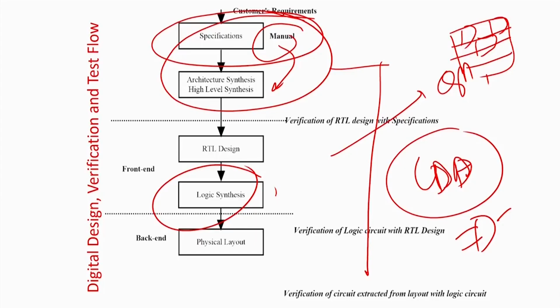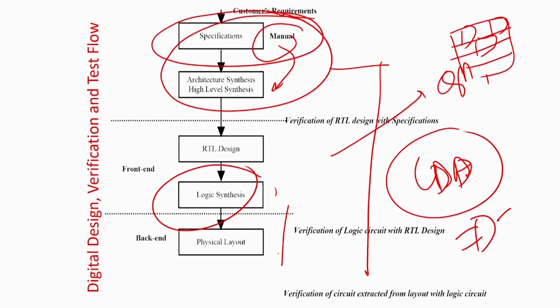If you want to bring it closer, then I have a very small circuit and I have to put all the gates in it. But if you make it too small, then you may not be able to put all the gates, and routing may not be feasible. So you should have a reasonable die size so that I can place the gates reasonably, not waste too much space, and still complete the circuit. Again, nobody can do it manually; there are algorithms to do that. Optimization in this case means how you can get a compact layout, but also that the compact layout should not take years to solve. From the gate level, I should not take years to generate that compact layout; I should get it in a reasonable amount of time.